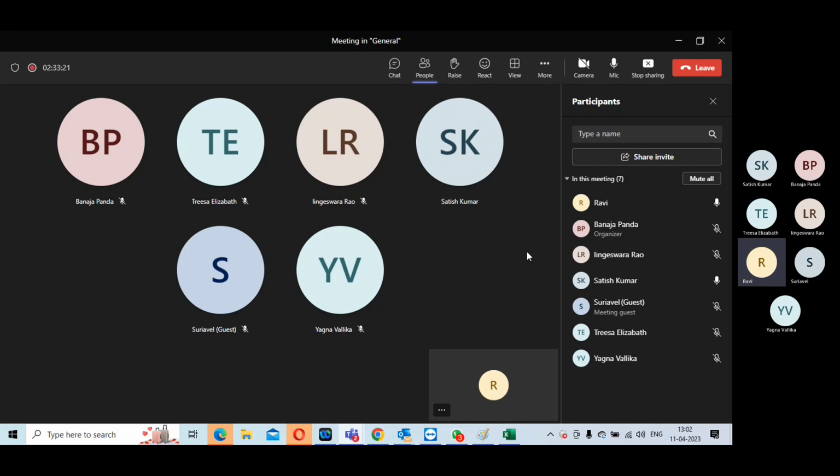See, in the lower node technologies, the color code should be there properly. The M1 metal layer and macro color code should align. Alternate means you can reverse the color and still make it work. But the macro color codes mean red and yellow in double patterning, triple patterning layers; they have to line up. The track should be proper. You have to take care of grid positioning properly, and make macro to macro position proper. There is a set of rules already given. Follow those foundry guidelines when you are doing floor plan.